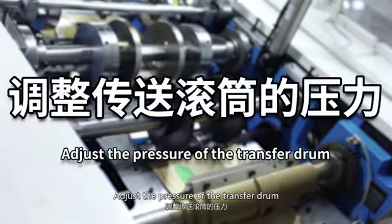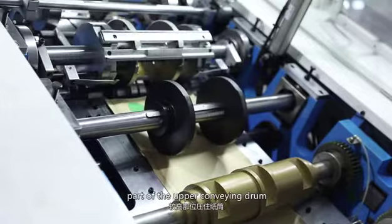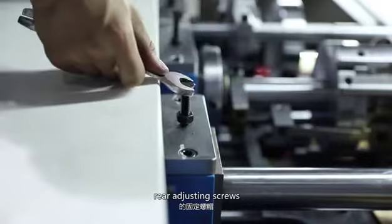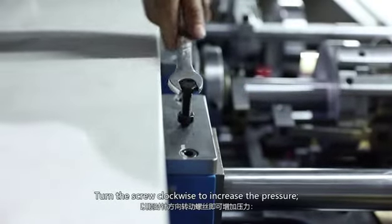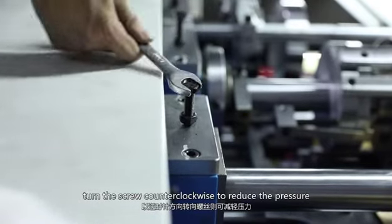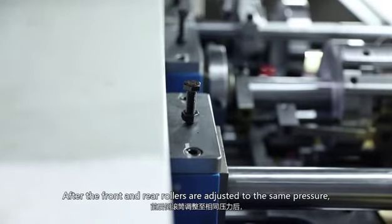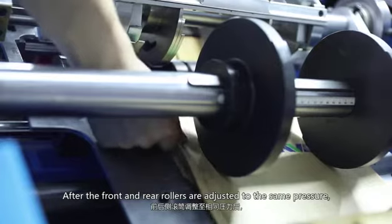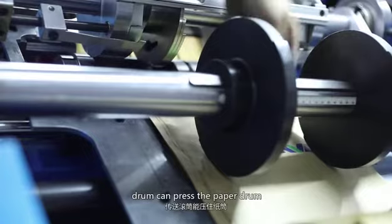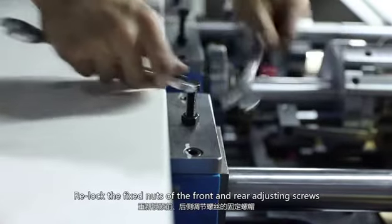Adjust the pressure of the transfer drum. Press the paper tube with the higher part of the upper conveying drum. Loosen the fixed nuts of the front and rear adjusting screws. Turn the screw clockwise to increase the pressure. Turn the screw counterclockwise to reduce the pressure. After the front and rear rollers are adjusted to the same pressure, pull the paper drum to confirm that the transfer drum can press the paper drum. Relock the fixed nuts of the front and rear adjusting screws.